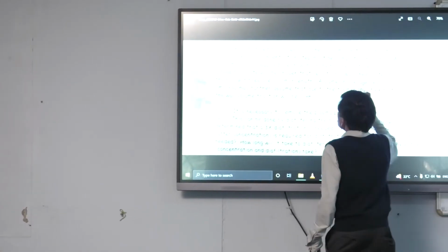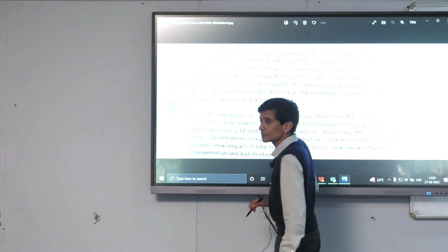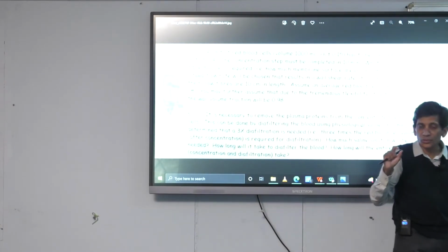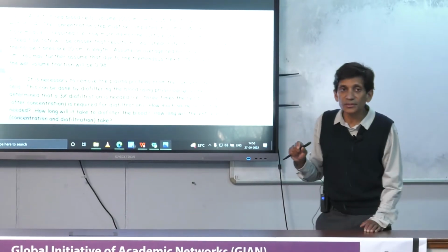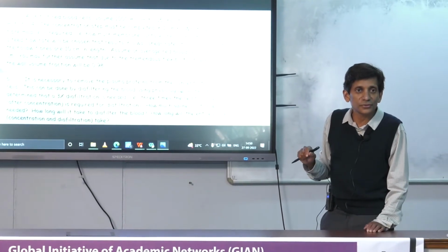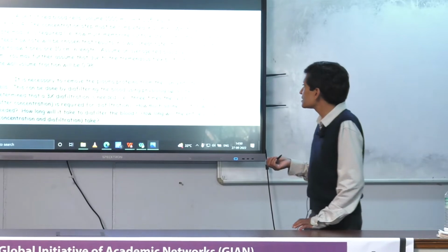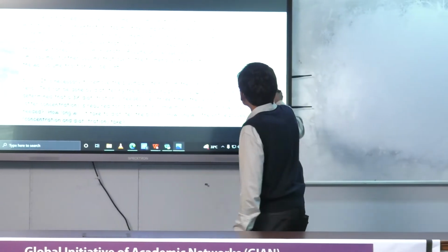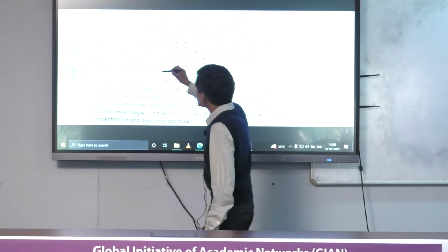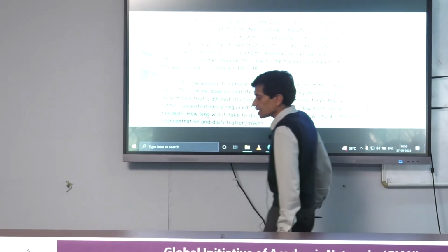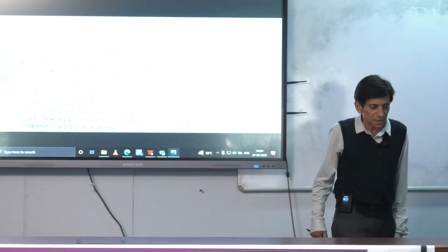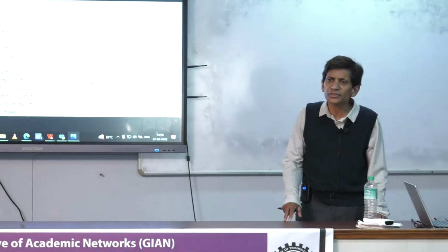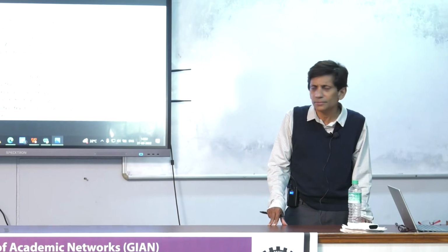So it has to be concentrated to a hematocrit of 0.4. So from 15%, you want to concentrate it to 40%. So the first question is, what do you have to do? Red blood cells are 2.6 micron, so you would have to use a microfiltration membrane, right? That's the best thing to do.